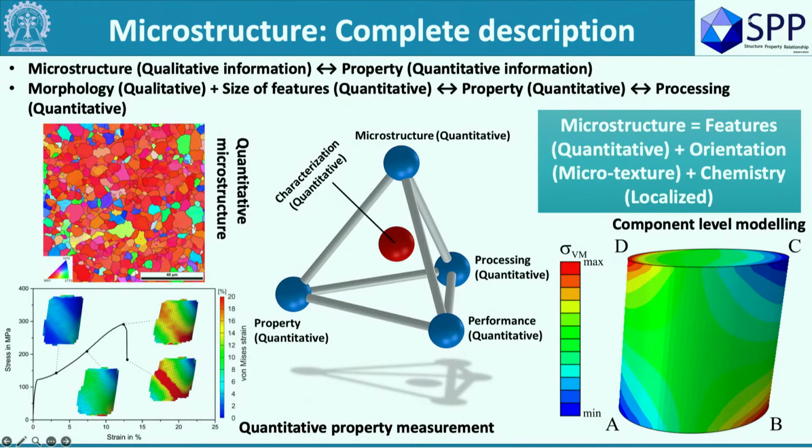Fortunately, when we were growing up as researchers, this one fantastic technique was coming out, called EBSD, electron backscatter diffraction, and with that this term also started coming in, microtexture. So microtexture doesn't always mean texture at the micron level. To me, it's basically the connection between a microstructure and a texture, at a level which is within the microstructural level.